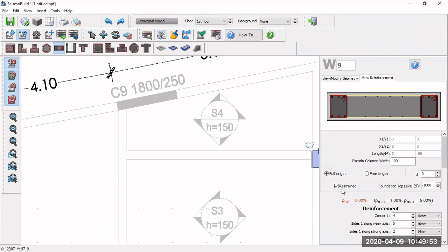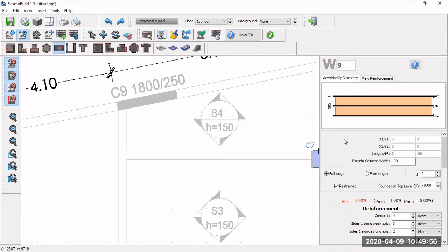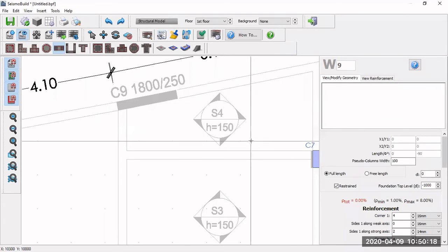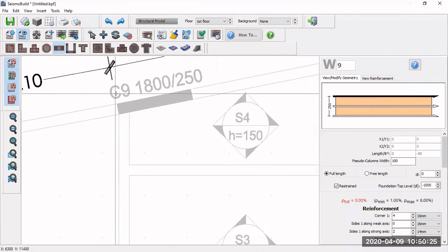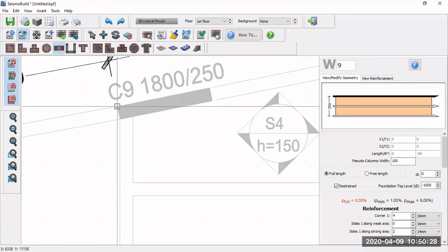So now we're going to show you how to insert the wall. So for the wall, if you look into this wall here, you notice that there's 3 parallel lines. These parallel lines indicate the line of how you insert the walls. So in this particular wall here, you can either insert at the middle line here, but in this particular example, it will be easier. We start from the corner. All right. So you select which line you want, and for instance, I select the top line. So I will move here. From here, I will click my wall.